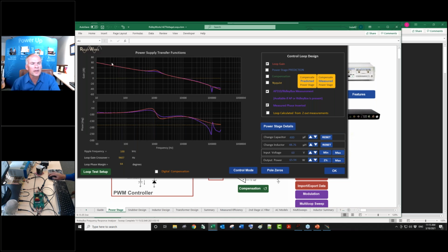This is perfect. The gain there is perfect. The gain there is perfect. The phase around the resonance is, well, that's 10, 15 degrees off there. Same there, which means the Q of the resonance is bad. Okay. And then, let's say the op amp is probably giving up here. The gain bandwidth of the op amp is very often not what they say it is. And that's why we keep these sweeps going beyond the crossover. You've got to see, well, what's happening here? This is dropping off, right?